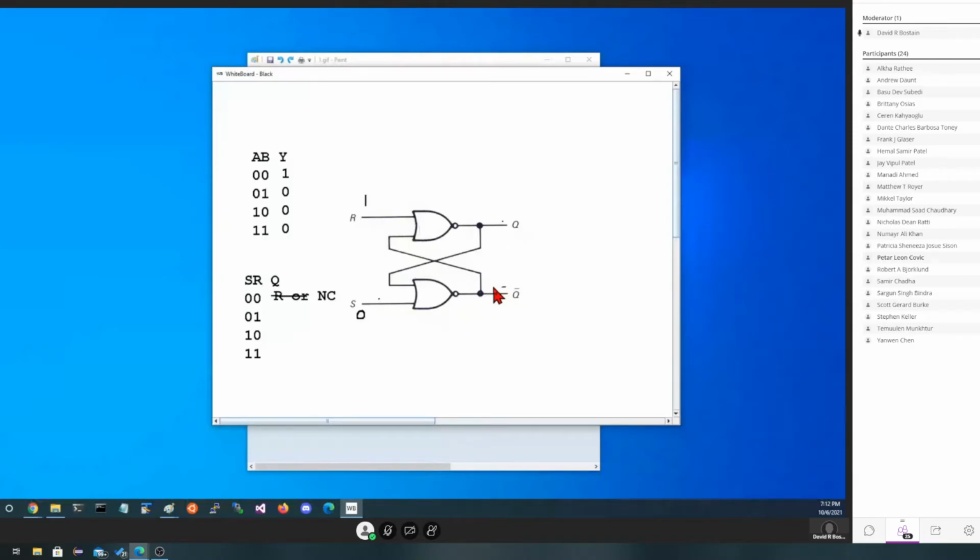But the only way to get a 1 is with a line in the table that has 2 zeros. So this guy can never be a 1 over here because he has a 1. So the only way I can get a 0 here is to put a 0 there, which means his output has to be a 0, which supports the notion that anything else gives me a 1 over here. And that 1 is reset, or not Q. So this is the reset signal. We could either write it as reset, or more likely we'd write not Q, and just not say that.